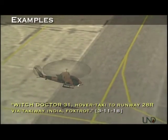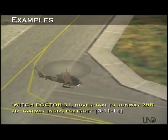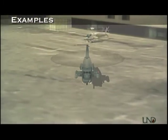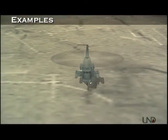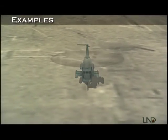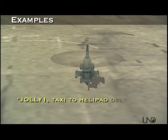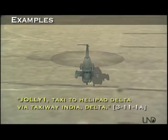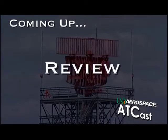Note that the phraseology is almost identical to the last example, the only difference being the type of taxi issued to the helicopter. Let's look at one last example. Jolly 1 is ready to taxi, and for this example it will be going to helipad Delta. Since this is a wheeled helicopter, you can instruct it to taxi just like a fixed-wing aircraft. The phraseology would simply be, Jolly 1, taxi to helipad Delta via taxiway India, Delta. Coming up next, we'll review the key points from this episode.